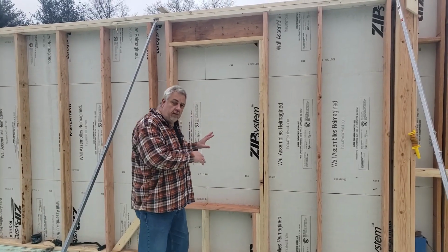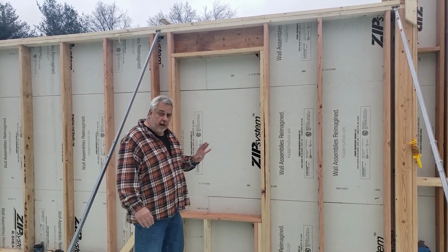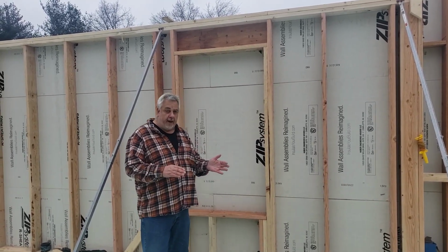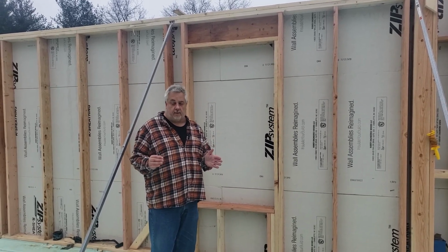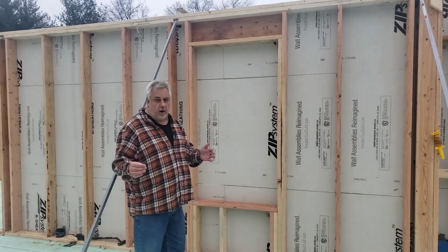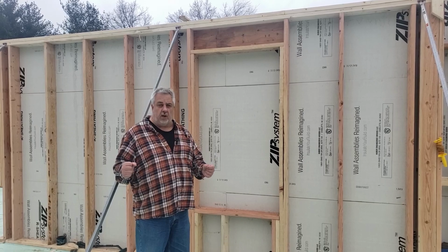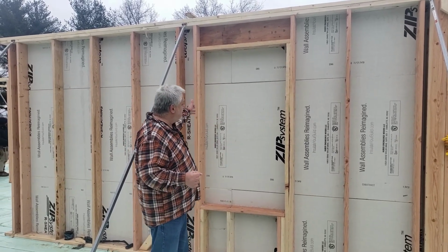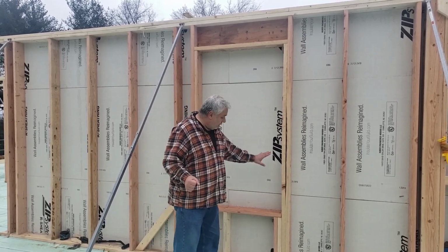All right, so we moved over to another section of the house. You can see this is a much smaller window, and conforming to the structural engineer's request, any window opening up to and including 3 feet can have a single jack. Anything that exceeds 3 feet moves on to a double jack. And then we do have some cases where maybe the windows are large enough where we get either an engineered wood column or the jack becomes a different system. But here you can see this is a smaller than 3-foot window, hence all of the components are the same.